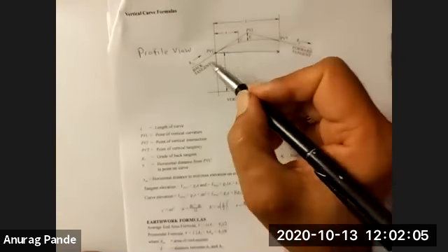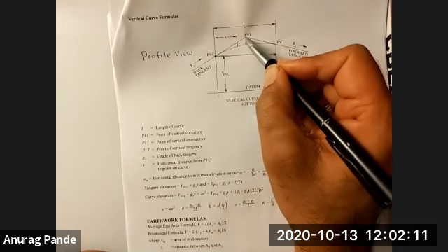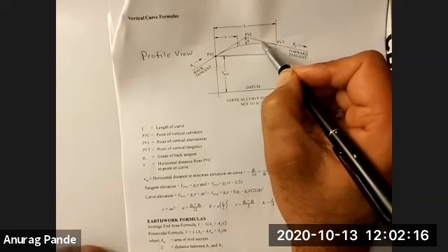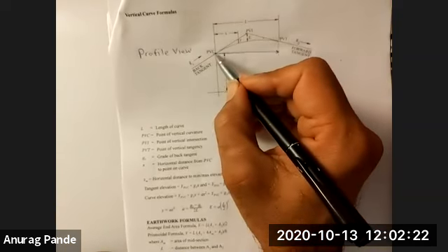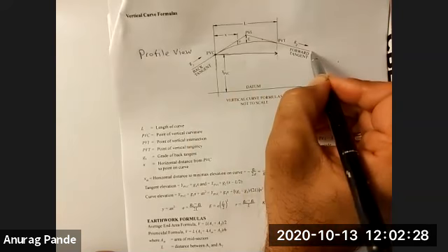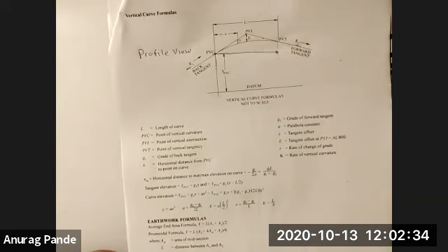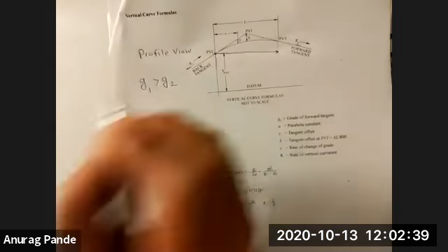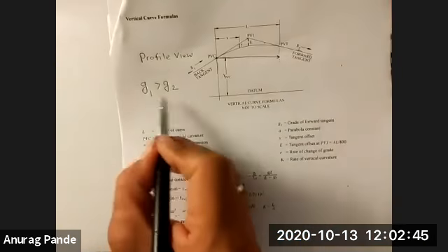And obviously, you don't want to be in a situation where the roadway goes like this, and then there is a discontinuous point on the road, and then you have to make a very sudden transition onto a downgrade. Obviously, that's not how highway design works. The way it works is that you want to provide a smooth transition between going up and then going down. So there is a G1 grade going up here in this figure, and then a G2 grade going down. And anytime G1 is greater than G2, as is the case here, because G1 is positive and G2 is negative, you could say that G1 is greater than G2.